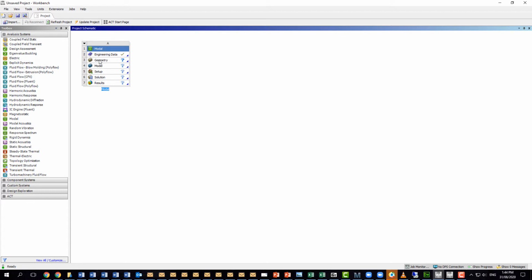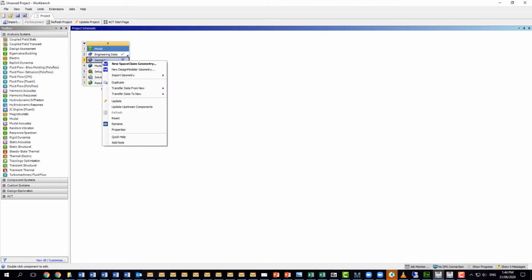All the other videos I've made were using the old software to define geometry. Basically in here, when you have a geometry, you right click. Remember in the other tutorial, I just said double click here, but actually when you right click, there is an option of so-called SpaceClaim and DesignModeler.